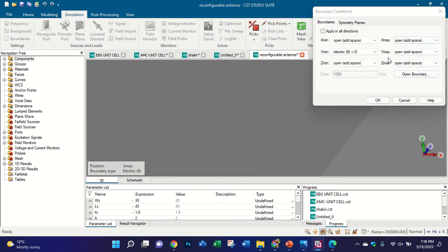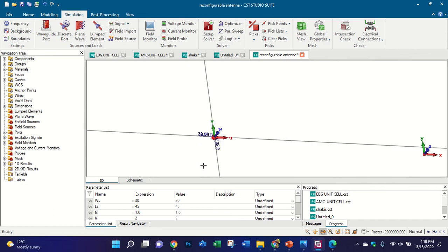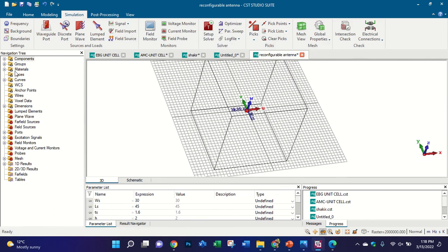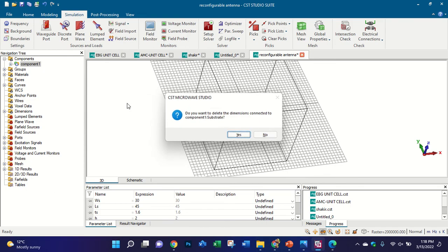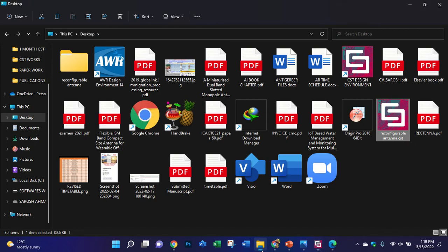And the second confusion is about when I want, Mr. Ahmed, I want to put these unit cells in the patch or the ground, not like a reflector or substrate. You understand me? I mean, when I want to put these unit cells in the patch, like isolation between MIMO antenna. When I simulate this unit cell before I put it in the antenna, what boundary condition must I choose?